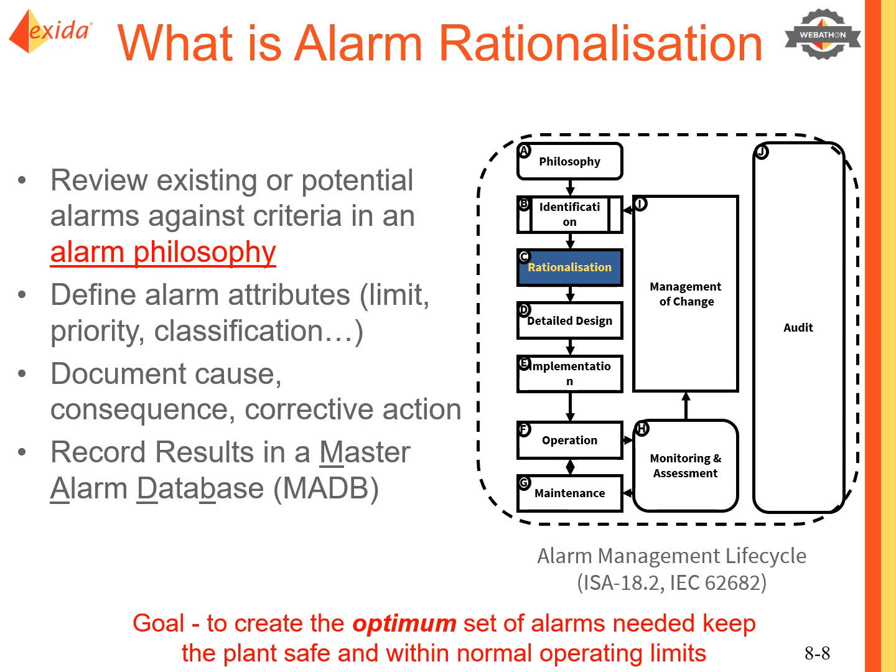We've also got to carefully go through the P&IDs and the complete IO lists or databases to check that we haven't missed anything. And by cross-checking these documents, we're very likely to catch the need for alarms that have been missed, or identify those alarms currently configured that don't, in fact, need to be alarms.